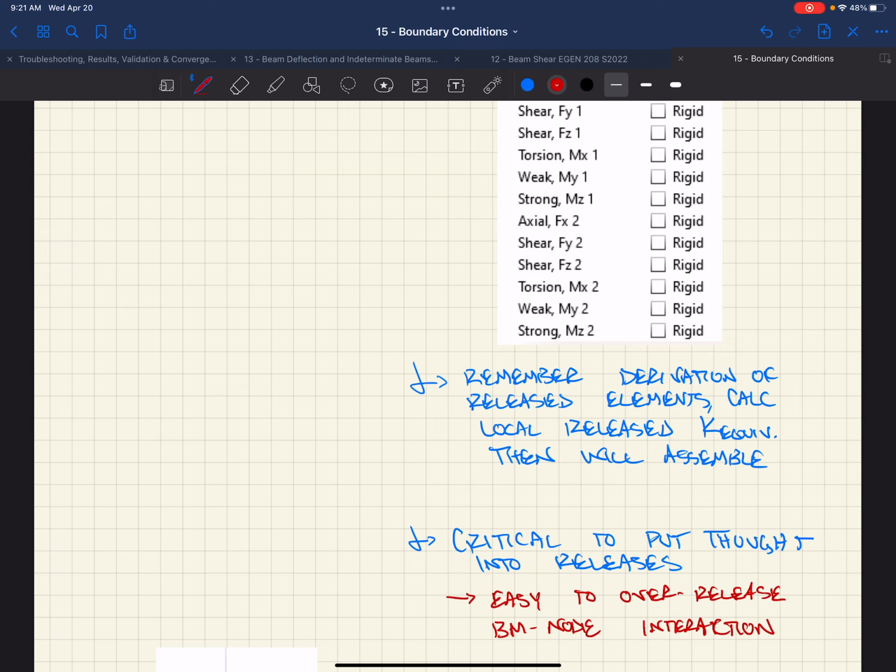What you would want to do is, if these are pins in real life, which in a brace frame you generally assume they are, and you have it in a larger frame model like the tower or something like that, then when you load it in the other direction, and maybe there's a diaphragm, a concrete on metal deck or something, connecting all of this, the stiffness of this thing bending in this direction is going to affect the overall performance of the model. Then you have to think about it and decide: should I release it or not? I would typically release it.